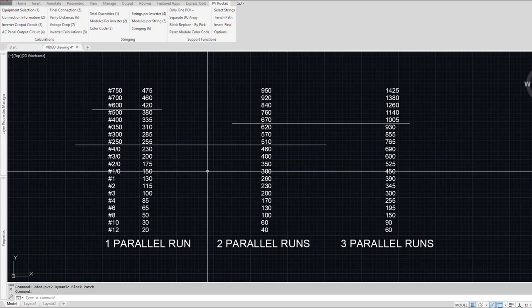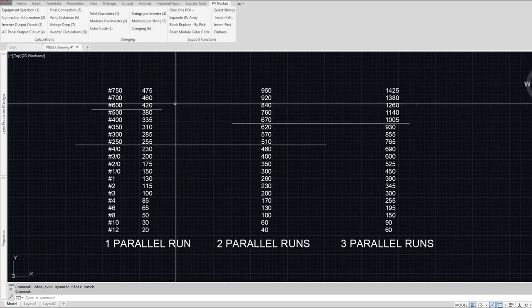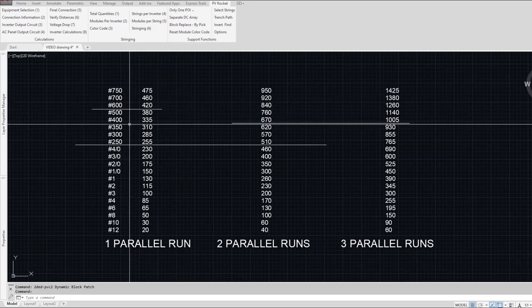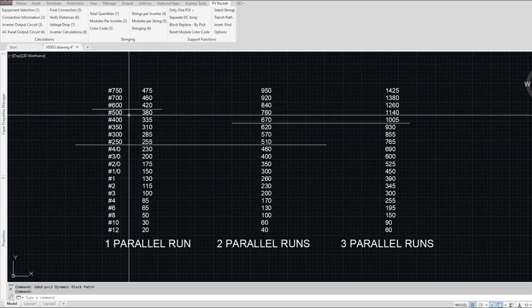But one way of overcoming the latter and doing what you want to do is to set a maximum conductor size. And that was how we did it originally. We got a lot of people that said, coincidentally, I drew a line here at 500, and that's where the line in the sand has been drawn by a lot of our customers. They don't want their electricians to pull 750 copper. If you've ever tried that or seen somebody try it, that is not fun at all. That is a lot of work.